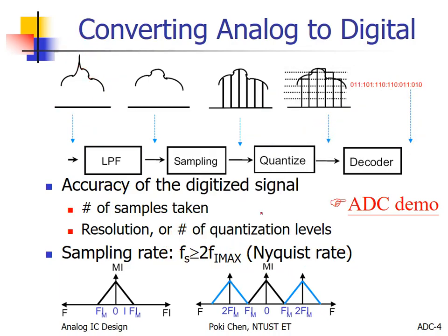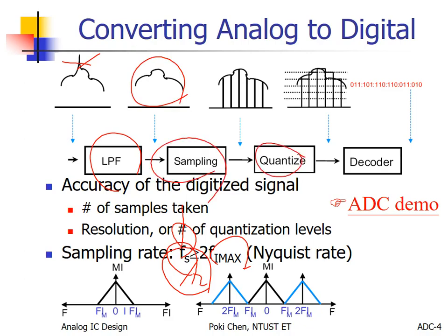Again, after you decide or you get some chip from TI, from National Semiconductor, and so on, you will see the sampling frequency is fixed. So the maximum frequency you can have for your input is the sampling frequency divided by 2. Above it, we need to filter out, usually with a low-pass filter. After that, we remove the too high frequency to be handled. Then you get this, and we can do sampling, quantization.